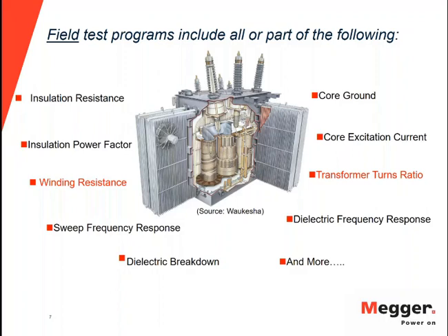For instance, if you want to evaluate the condition of insulation, you would perform insulation resistance and power factor testing. Likewise, if you want to check the condition of the core, you would perform tests like excitation current, core ground, those kind of tests.